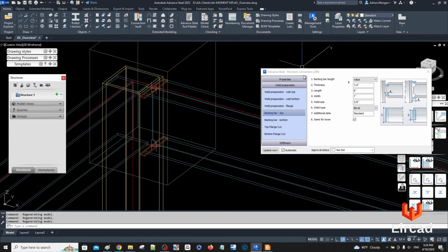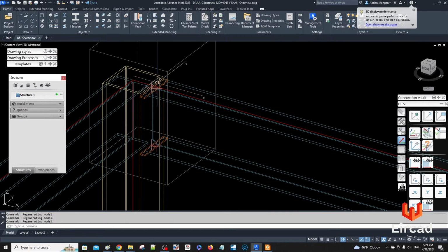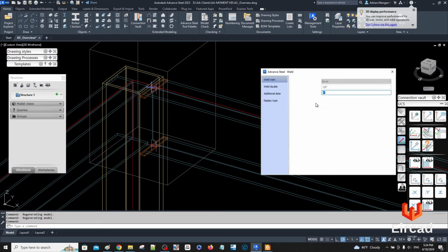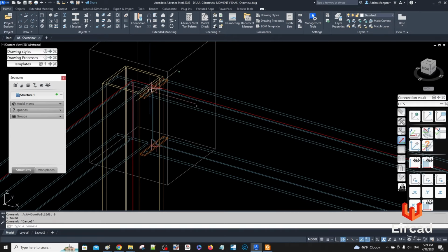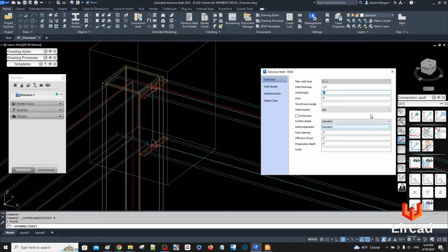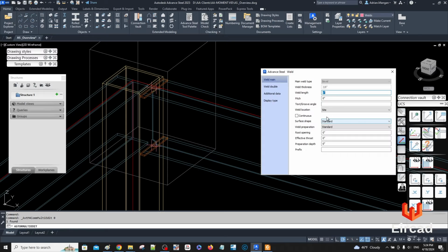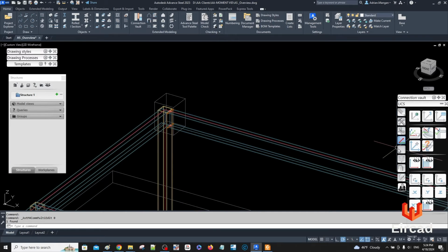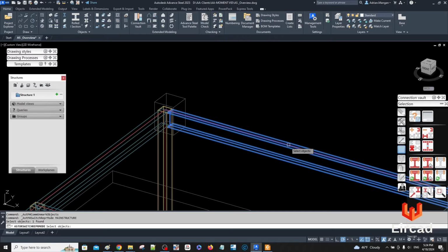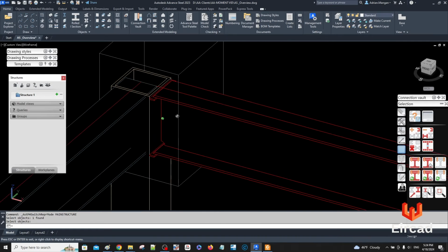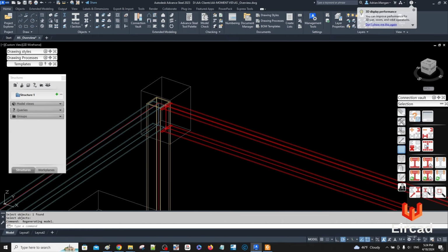Alright, so that's probably good. You just check your welds here. So if I go in here, click on this weld, that's a site weld, and this one is a site weld. I can have that as a shop weld, and we'll tack weld them in the shop. Now if I select what's connected in the shop, that's what's connected in the shop.